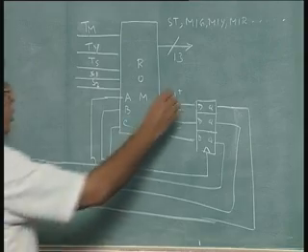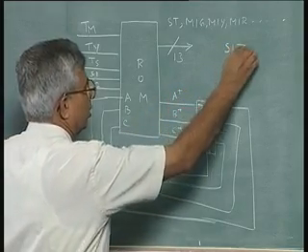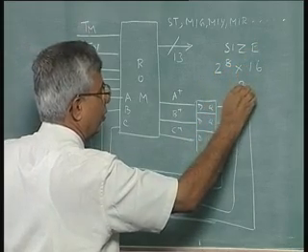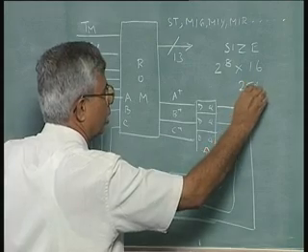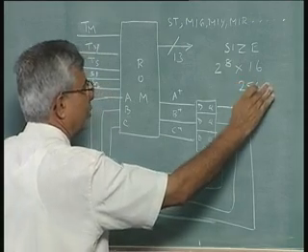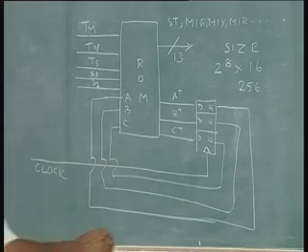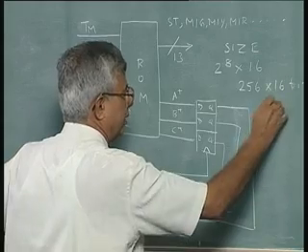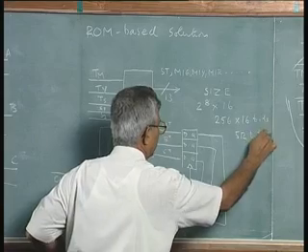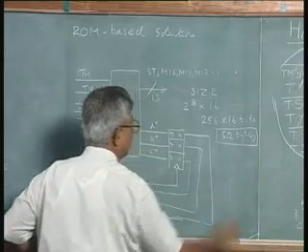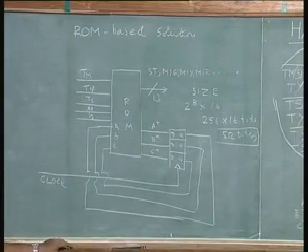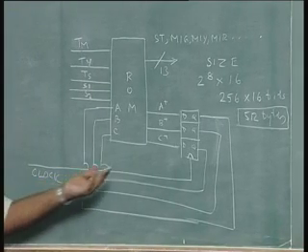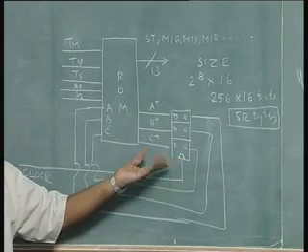So, the size is 2 power 8 into 16, which is 256 into 16 bits, or 512 bytes. We have a 512 bytes ROM, or byte organized ROM, 512 words. I can realize this. All we need is, in addition, 3 flip flops. This is a ROM based solution.